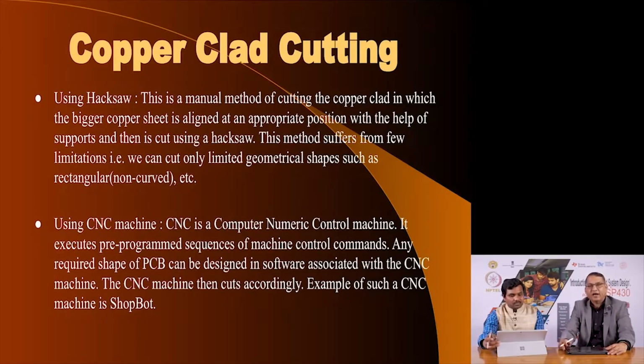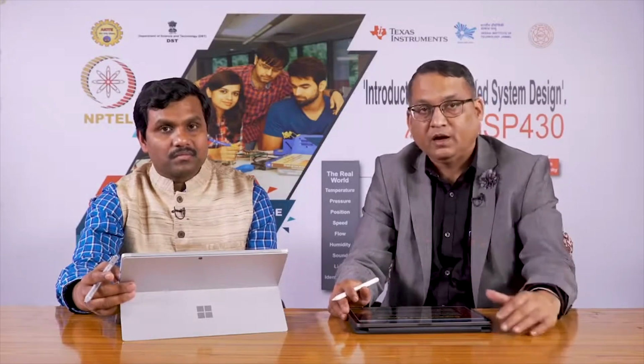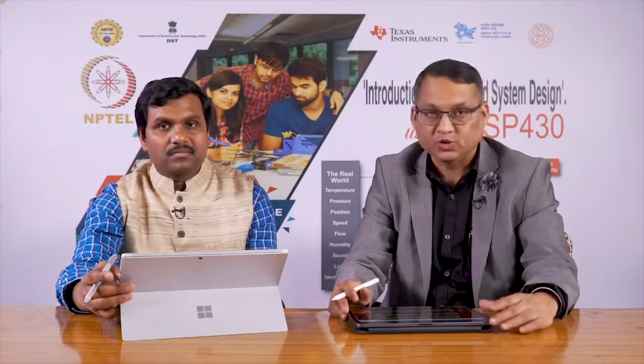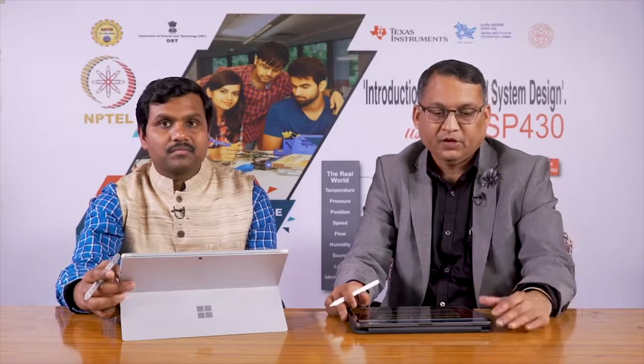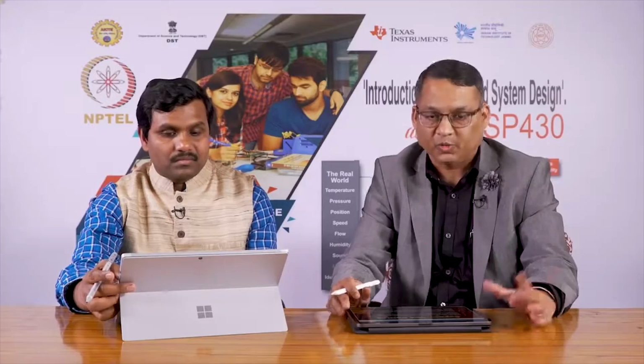Or if you have access to a computer numerical control machine called a CNC machine, then you can program it to cut it of exactly the same dimension as you want. You can also have that CNC machine drill holes, especially the mounting holes or other holes also. And this method is very good if you want to fabricate several, say 20 PCBs. Using the hacksaw method will be manually taxing and may take more effort, but if you do not have a CNC machine, that certainly can be used. So, you first cut a copper clad board of appropriate size.